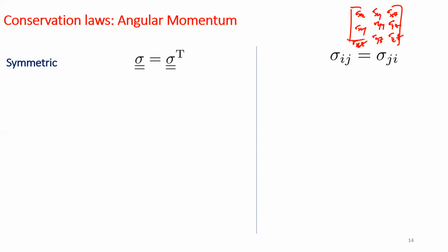Originally, when we defined stress using the Cauchy's notation, it was defined as traction T equals sigma transpose n hat. So stress was a function mapping a first order tensor to another first order tensor, and that's why stress became a second order tensor. Stress was a function mapping a first order tensor, which is the unit normal to the surface, towards the traction, which is again a first order tensor, or specifically a vector.